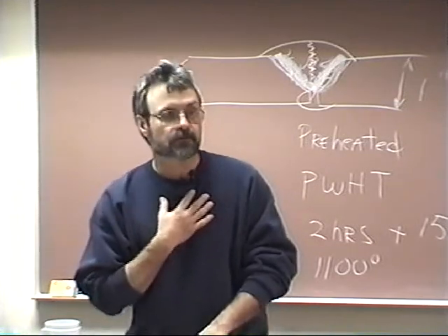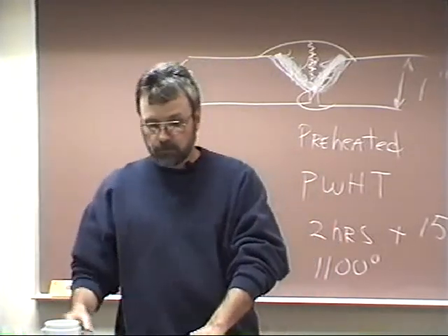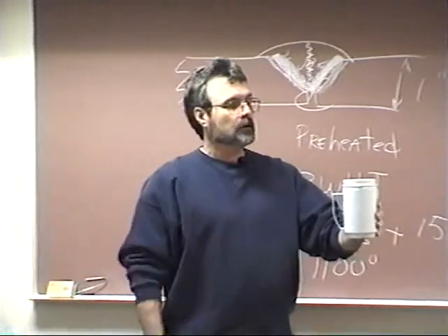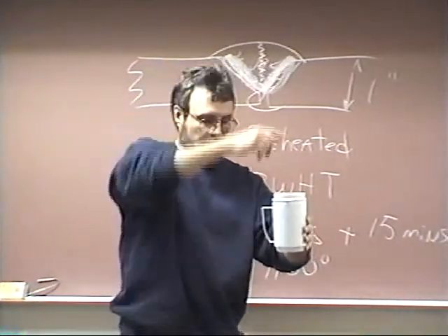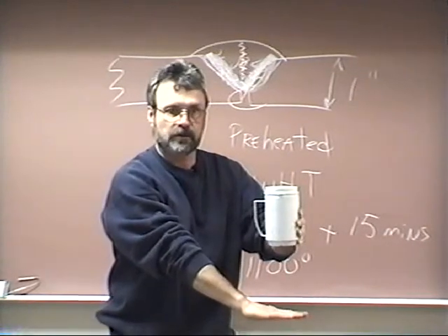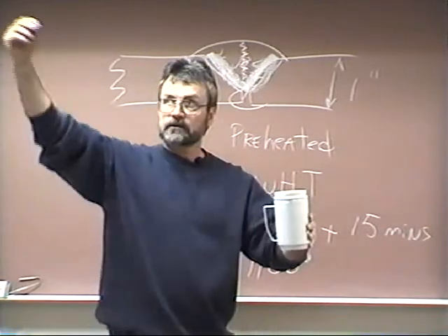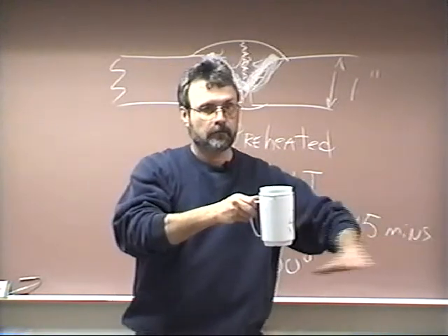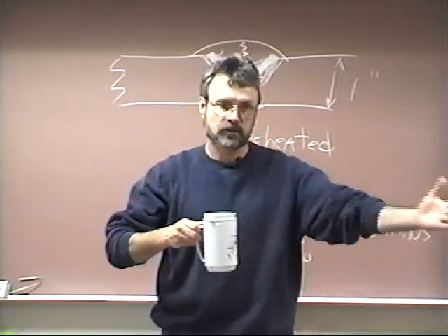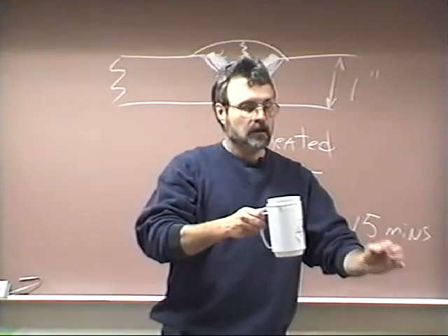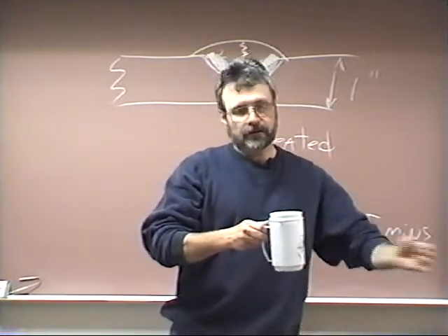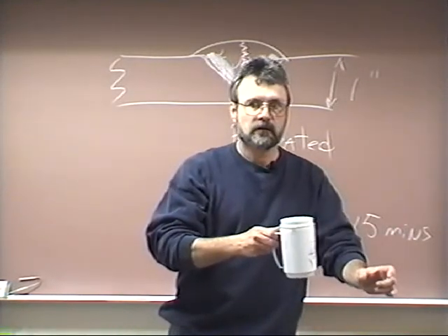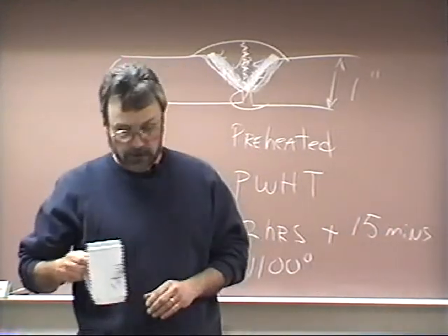And so there's such a phenomenon in X-rays called blow-up. Say I wanted to X-ray this cup. Well, if I had my source up here and I shot it, then I'd get a nice little flat two-dimensional picture right here. But if I had my source over here and I shot it, now I'm going to get a blown-out picture, just like the sun casting a shadow. And so that may fool a welder into thinking the defect is over here when the defect's actually over here. And so you want to check that to make sure that they've gotten it all out.